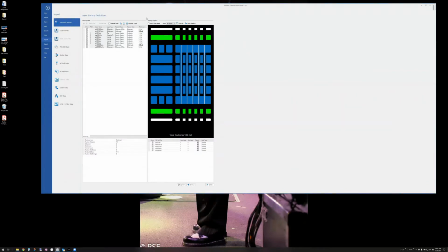it takes me to a new feature called the Stack Up Visualizer, where basically instead of having to go and tell the software that I have this drill file only goes through layers 1 to 3, and having to click on, as you did in the past, layer 1, layer 2, layer 3, and then you'd have to do the same for this one and same for this one. It's just a drag operation. So I just drag that up there to indicate that the drills are going through the proper layers. And I could do that for all 3 of my partial drills here.